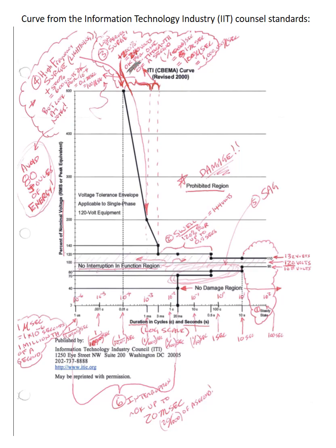But you can handle certain high voltage surges up to a certain amount. You can see there, I said high frequency surge lightning. That's plus 500%, equals 600 volts, for 10 to the negative fourth milliseconds. So 100 microseconds.